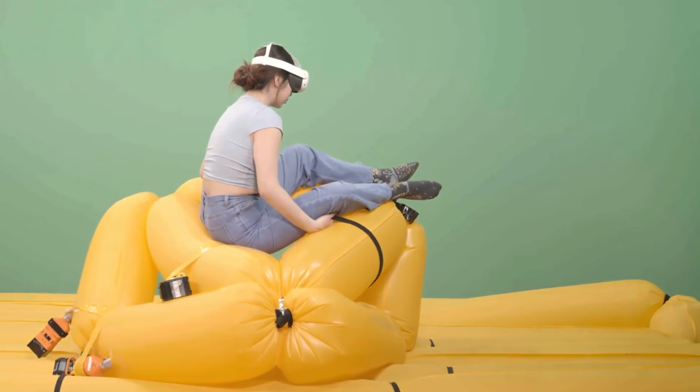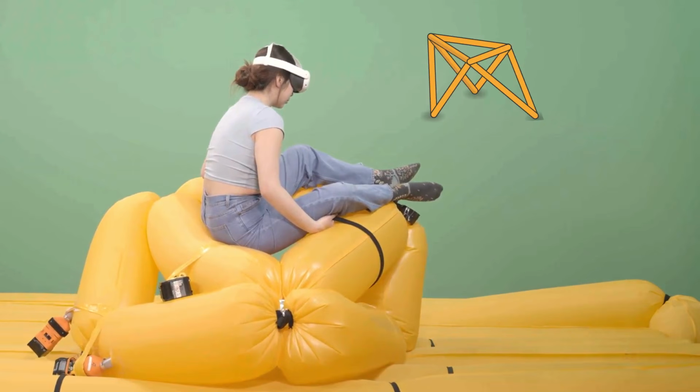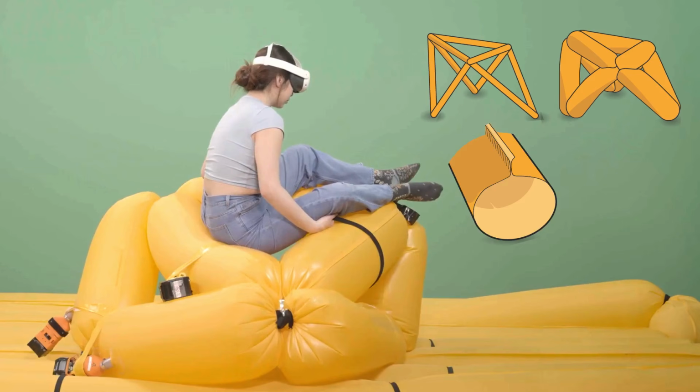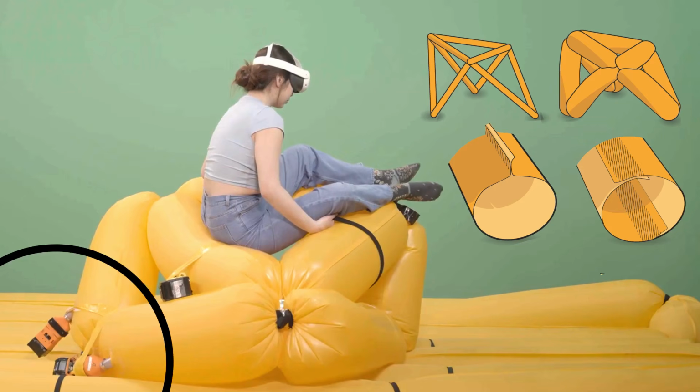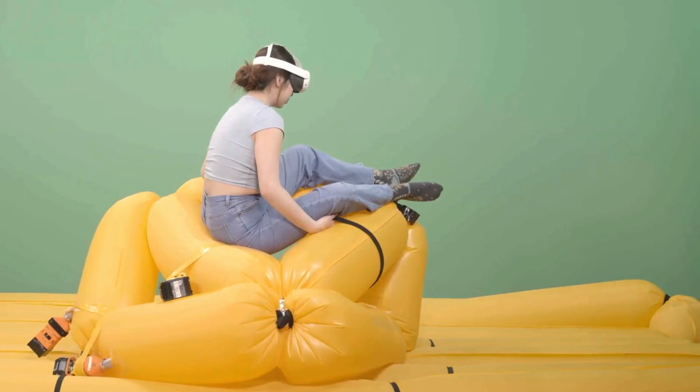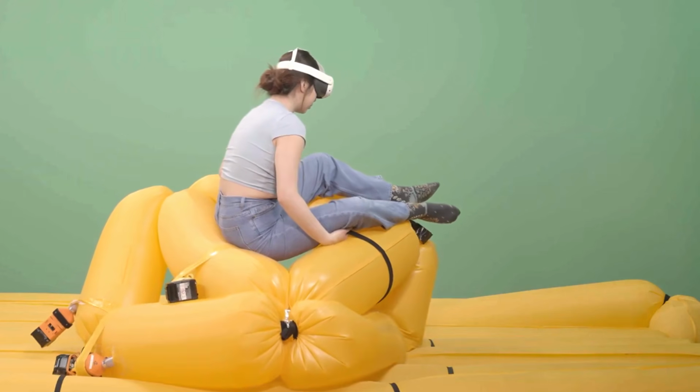We started our design iteration towards lifting human weight with traditional single-tube materials, but then tripled the tube's cross-section. Next, we replaced the traditional fin seals with lap seals. This allowed us to increase tube pressure by a factor of 4. Finally, we replaced compressors with custom blowers, which allowed us to produce 50 times higher airflow. Combined, these 3 modifications allow us to animate structures under load.